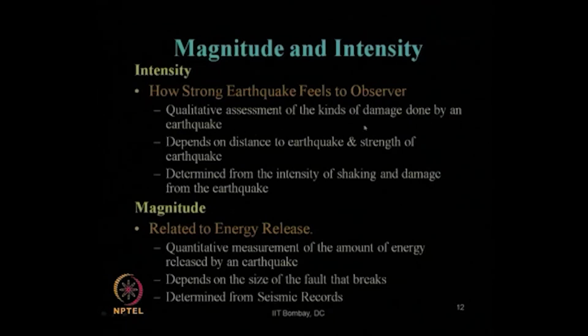From an observer, as well as from looking at various damages to structures, we can say, okay, this earthquake caused only superficial damage to the structure. So, not a big earthquake, but if it caused structural damage, then yes, it is a big earthquake. Like that, a qualitative assessment of the damage can also be used to obtain the intensity scale of an earthquake.